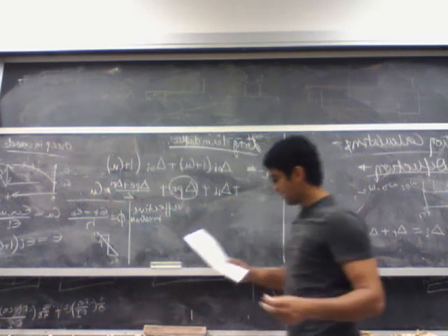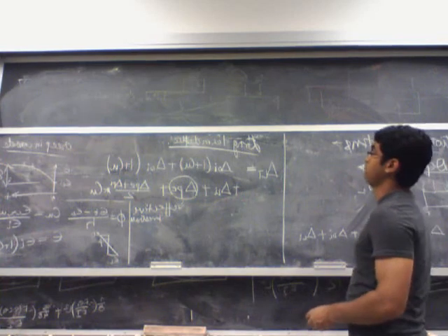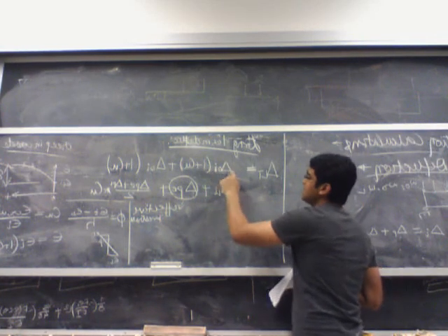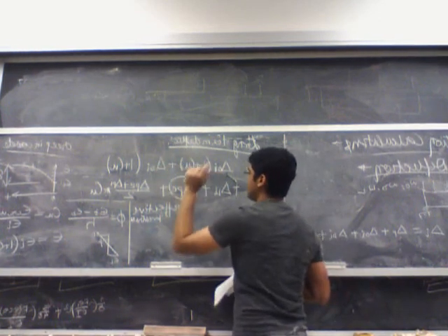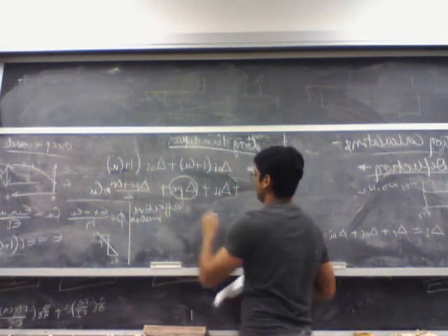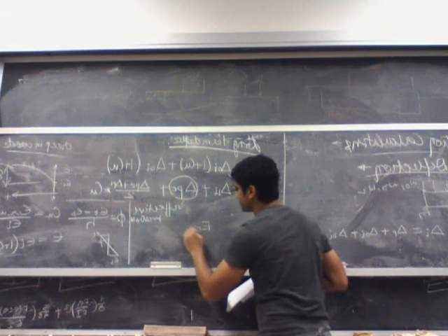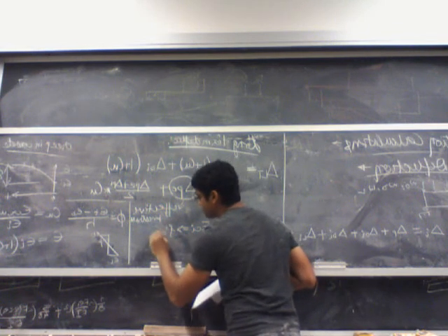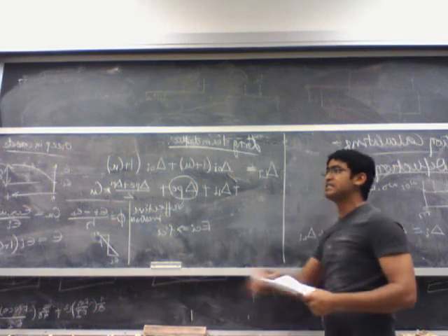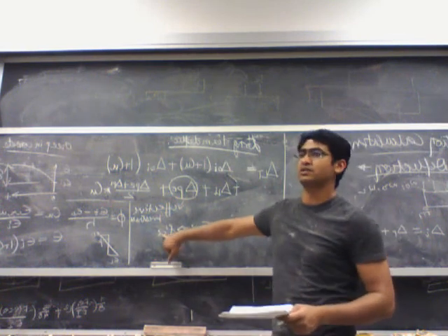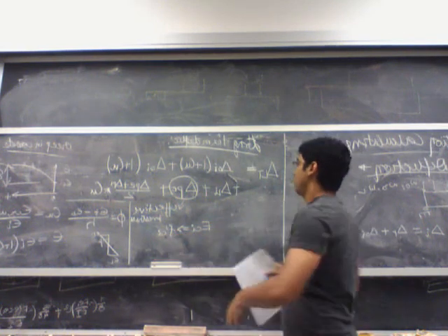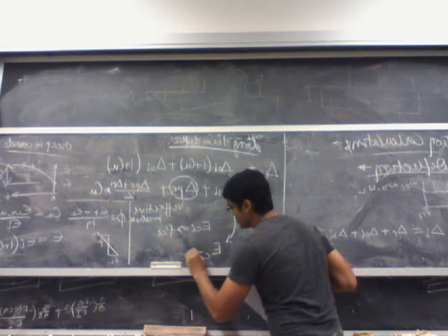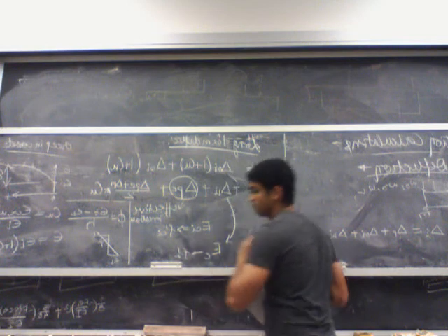One more thing. When calculating all these deflections, delta Oi, Di, Pe, and Pi, you always use Eci, which is based on f prime ci of the concrete. That is the initial strength of the concrete right after stress transfer. But in case of delta Li, you use Ec, which is based on f prime c.